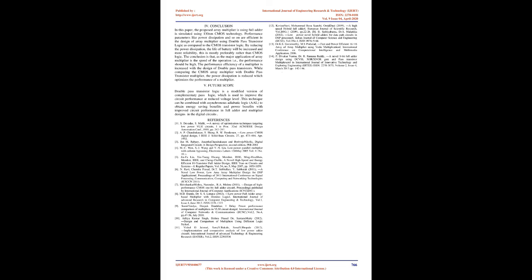For conclusion, in this paper, the proposed array multiplier using full adder is simulated using 130 nanometer CMOS technology. Performance parameters like power dissipation and so on are efficient in the design of array multiplier using double pass transistor logic as compared to the CMOS transistor logic. By reducing the power dissipation, the life of the battery will be increased and there is more reliability. This is mostly preferable rather than CMOS logic.